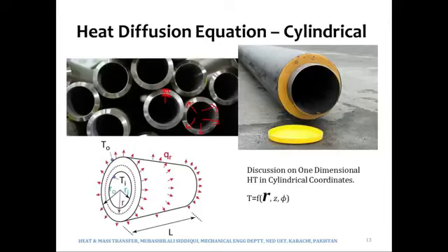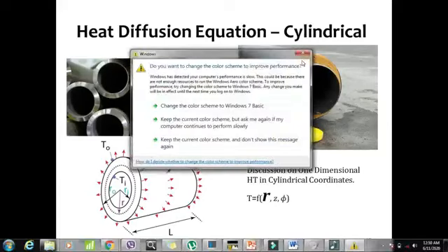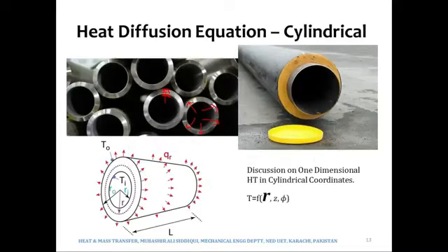So there are two advantages. Number one, the heat loss reduces to a minimum. Number two, putting a pipe in an insulation makes it a safe to touch environment. It prevents accidents, because if you now touch the outer surface, you will not feel that the pipe is hot, because you are not touching the pipe, but in fact the insulation.